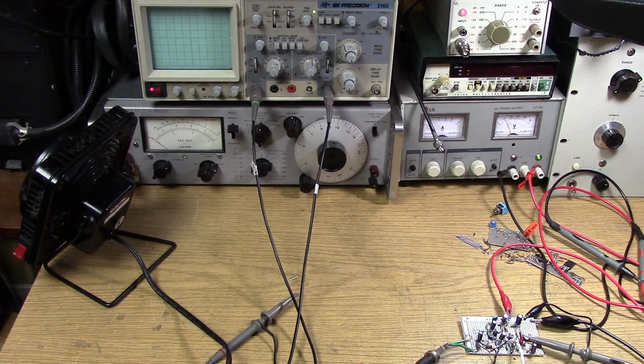So I'm looking at the output now, and this is with the gain pot on the preamp only at about a third. If I flip the switch, okay, I flip the switch, and now, as you can see, my voice is going down instead of up. That's why we have the phase reversal switch. We definitely want the positive peaks to go to the modulator.